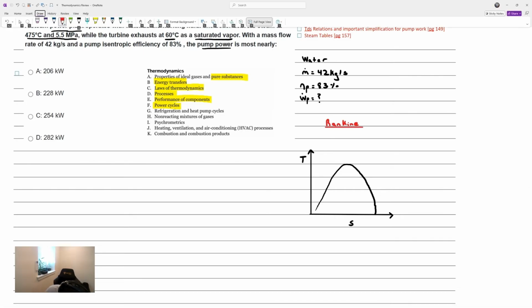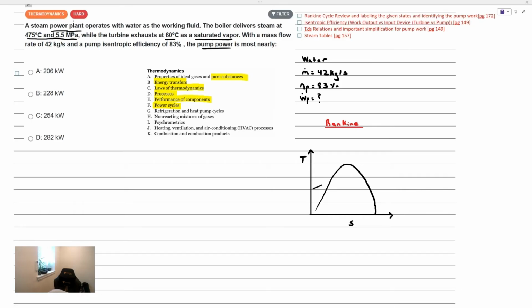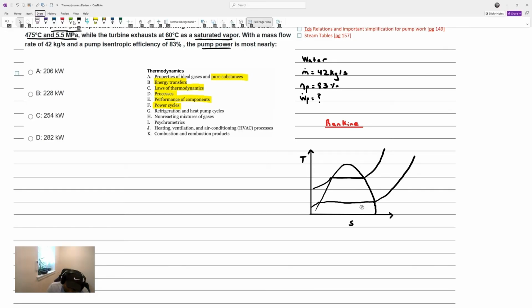And in general, the Rankine cycle operates between two pressures, one high pressure here and one low pressure here. Remember, those lines of pressures are like stair steps on a temperature. When the vertical axis is temperature, the pressure is kind of like a stair step. So let's start off here at state point 1.